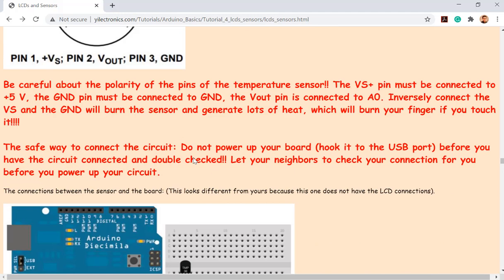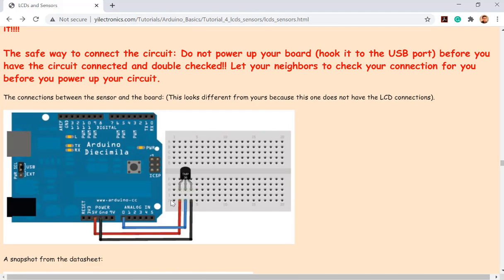Here's one thing you need to know. Definitely do not swap the ground and power, which will heat up this sensor really quickly. I believe some of you, if you took my Engineering 104, probably have tested this sensor in the past. If you swap the power line and ground line, the sensor will become super hot.